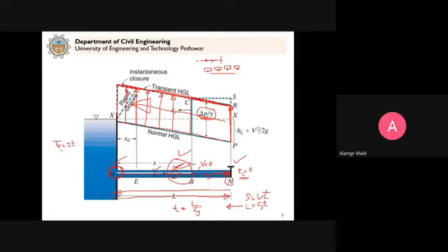So this will be equal to 2 times L divided by Cj. So the round trip for the pressure wave is 2L by Cj, because it is 2 times from N to M and then back.